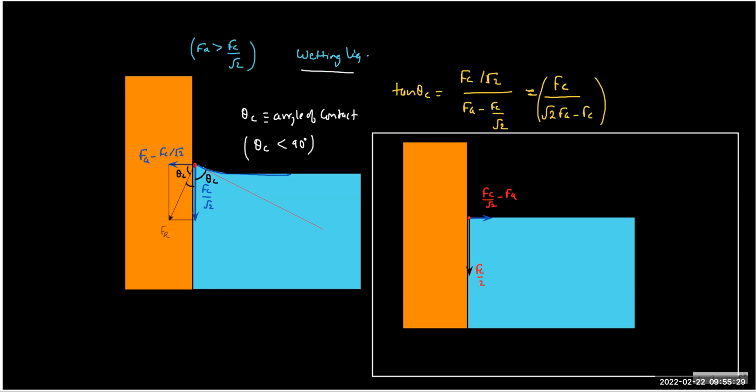Definitely the resultant in this particular case will be like this. You can see the resultant force comes on the right side instead of left. And as I told you, the property of a free surface is to always remain perpendicular to the resultant. You can easily understand this on your own by common sense. The free surface will try to be like this, so this is going to be the free surface, something like this.